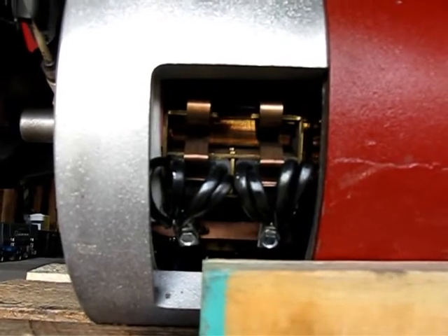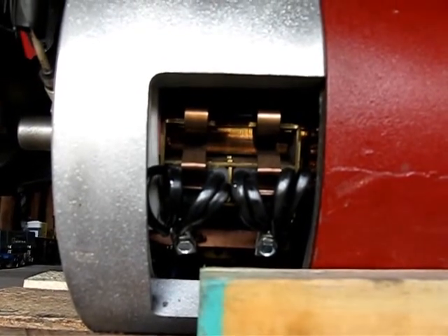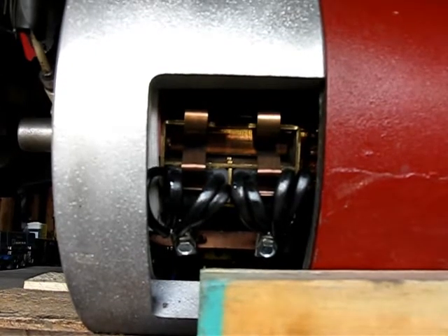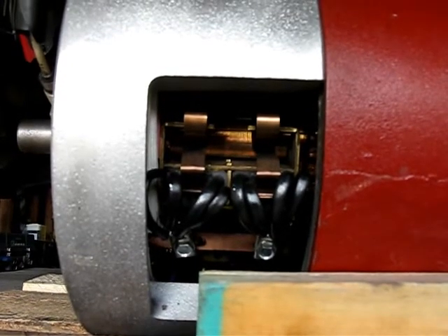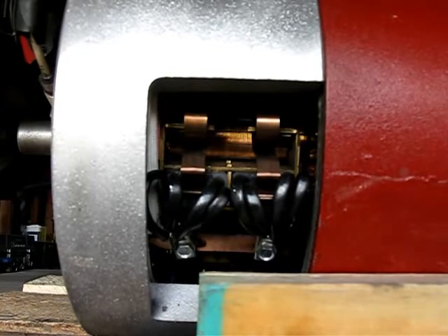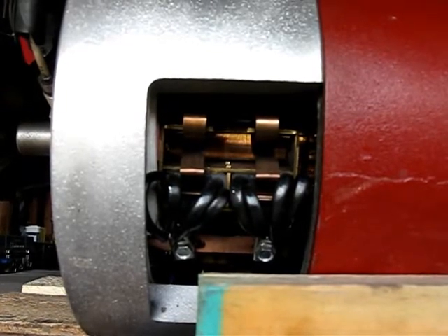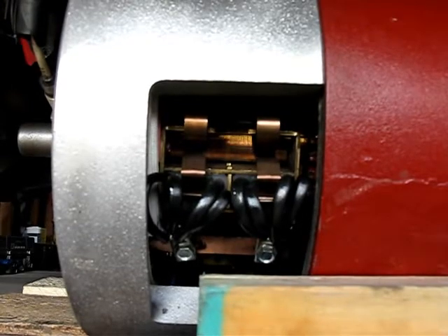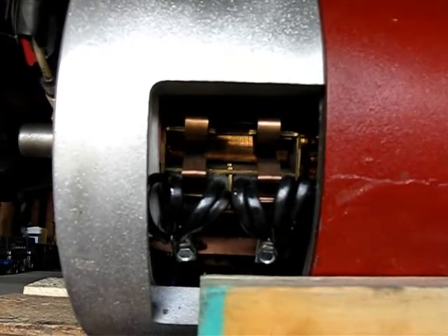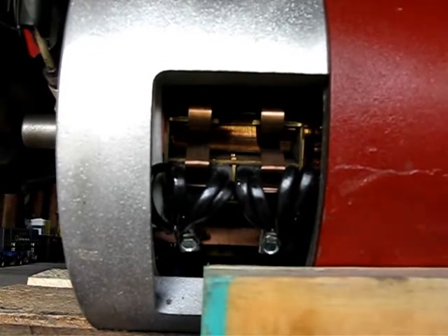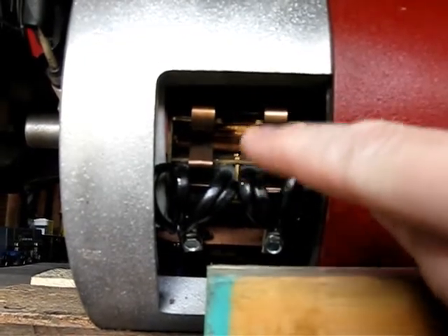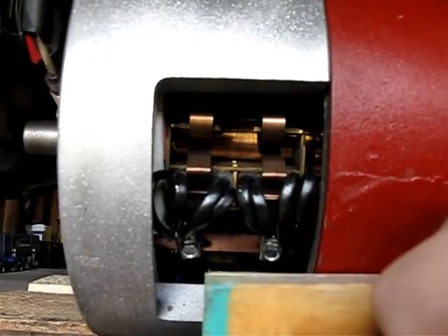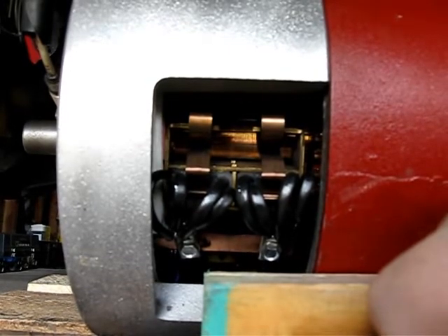So my commutator looks okay to me. I mean, there are striations here that you can tell that there's like wear marks of where the patina is starting to be deposited on the commutator. It's not very dark yet, but I can see like a line in the middle where it basically hadn't been rubbing on the brushes.